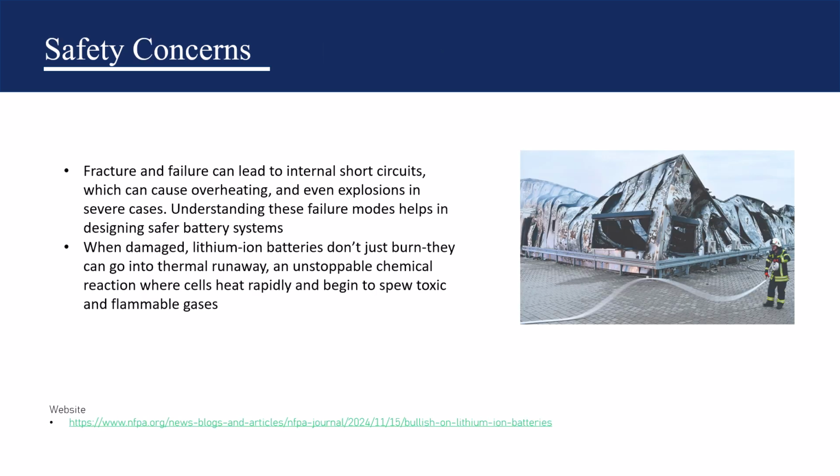Something else to consider is the safety concerns of batteries. Fracture and failure can lead to internal short circuits, which can cause overheating and even explosions in several cases. Understanding these failure modes help in designing safer battery systems. When damaged, lithium-ion batteries don't just burn. They can go into thermal runaways, an unstoppable chemical reaction where cells heat rapidly and begin to spew toxic and flammable gases. The picture shown shows what kind of damage these lithium batteries could do when they fail. So by studying these failures and fractures, we can prevent these incidents from happening.